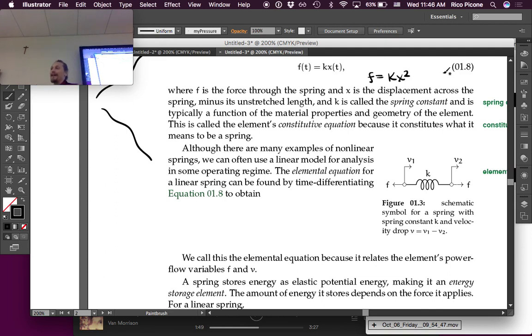For a mechanical spring that you buy, those operate linearly over a pretty wide displacement. Eventually, they will yield, and it will be very nonlinear. But even before they yield, they'll be a little nonlinear. Other types of materials that we model as springs usually become nonlinear real quick.